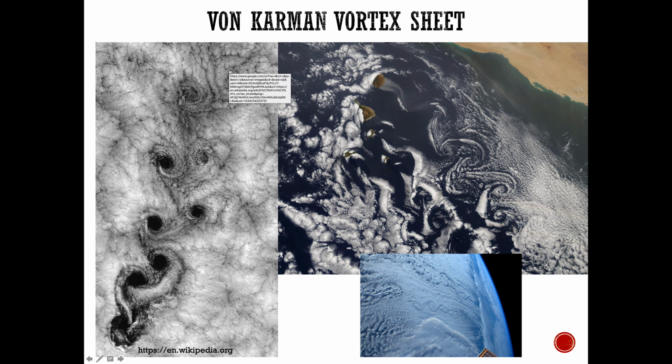Before we talk about that, here are some interesting von Karman vortex streets that appear in nature. We can see the vortex shedding of an island over here. Again, I believe these were taken by the International Space Station crew. Here you have some of the islands, and you can see the vortex shedding behind those islands, and you can also see the cloud right here. Which is pretty cool, right? You will see these patterns of vortex shedding a lot because it so happens that the Reynolds number at which this vortex shedding occurs is more common.